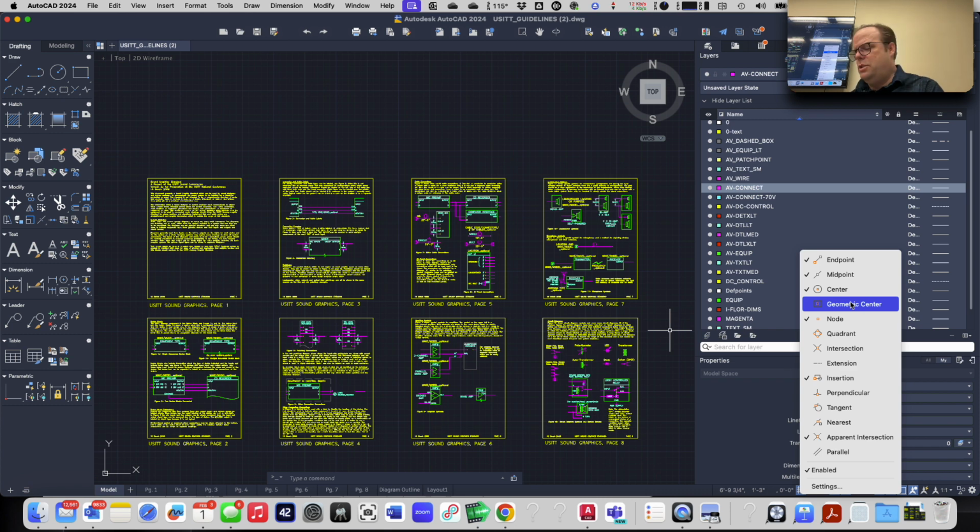Okay, because the mouse is this very imprecise tool, at least from an AutoCAD point of view, because the mouse doesn't know where XY is. And if you're not careful, you can just click anywhere in the AutoCAD model view, whether that's a number that makes any sense or not. But Object Snap allows your mouse to snap to parts of objects and lines that have already been drawn, so that you know for sure that you've clicked exactly on the end of that line. Okay? You don't have to guess.